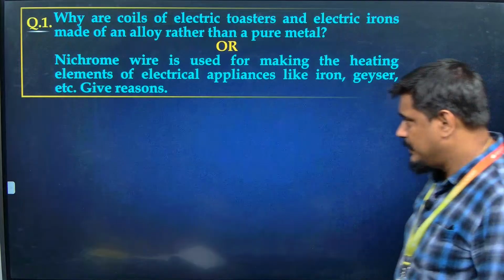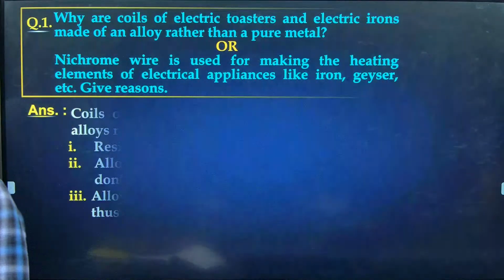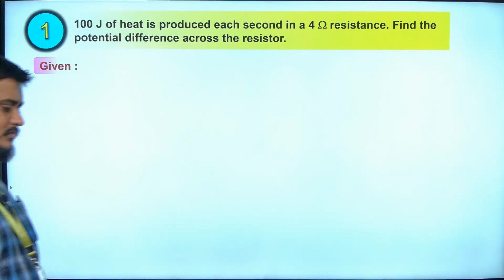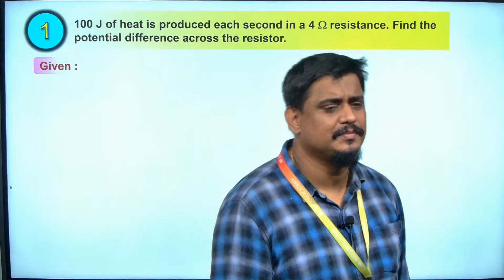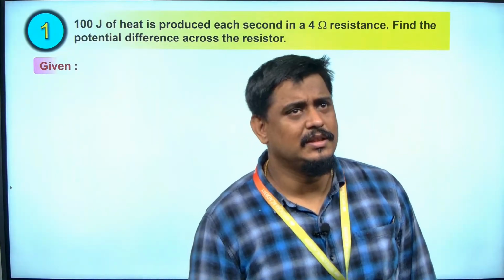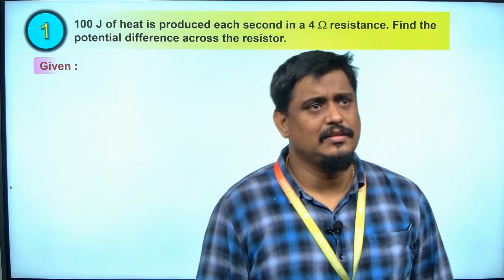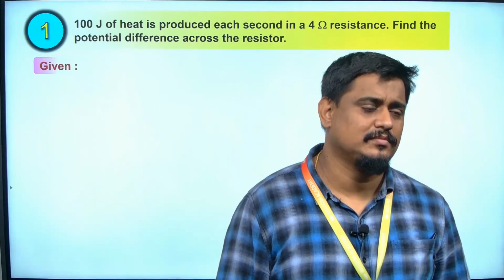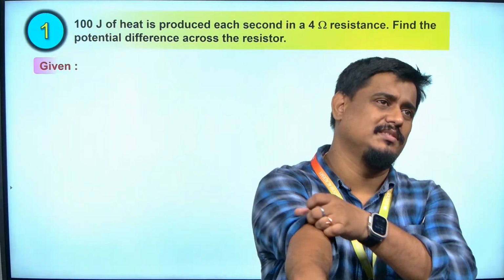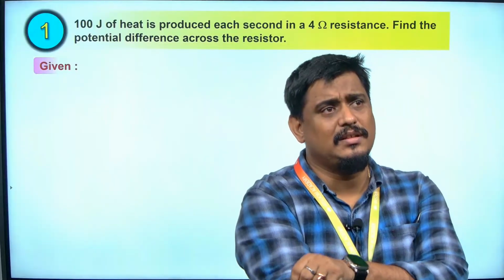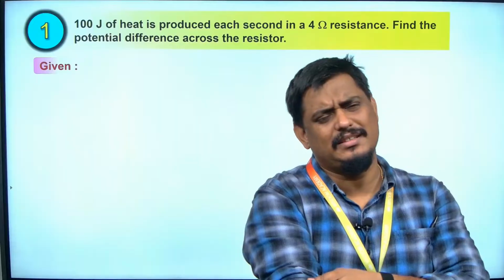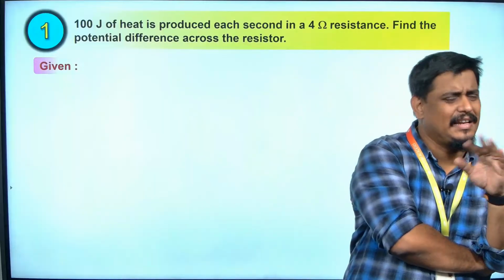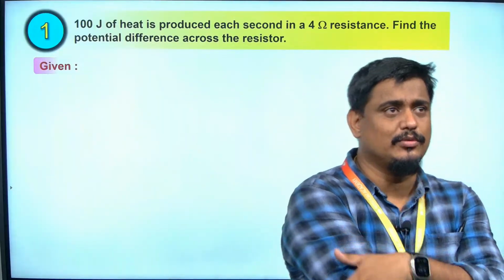Sir, if they ask, if the current for an appliance is like 7 ampere? Yes, but then the nearest rating is only 10 ampere. Yes, you can give the nearest value of available rating, 10 ampere you can give. Sir, if it goes to 10 ampere, the fuse won't break, but the appliance might get damaged? That much allowance is there. If it is working at 7 ampere, till 9, 10 ampere it will take actually. Practically I am speaking to you.